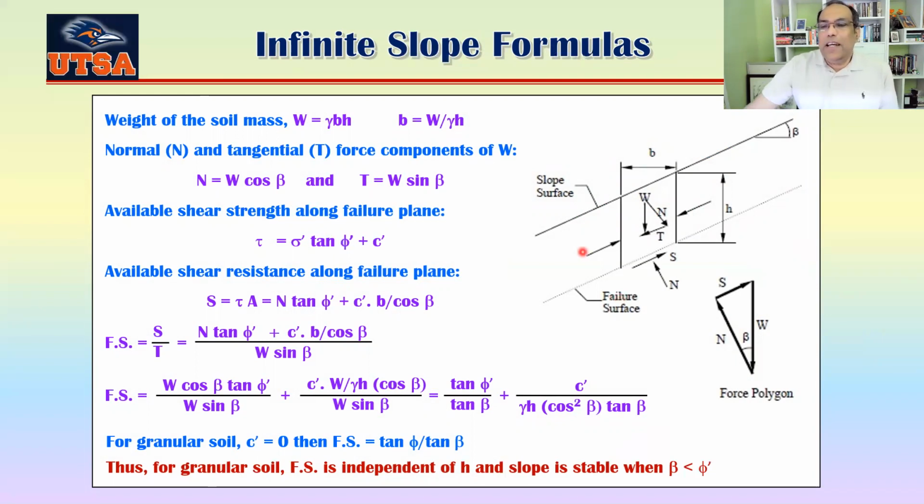Now you can see here that if I take a little slice here, this is the weight of that soil mass. This is the normal force. This is the shear force, okay? And let's say these forces are negligible in that case.